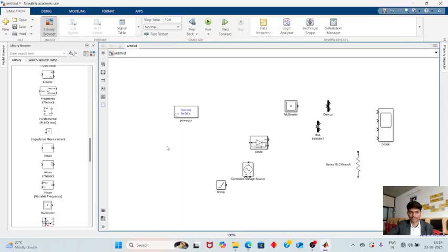Hello everyone, I am S7, roll number 15 from TY Electrical, and I am doing the simulation on the power diode. These are all the element blocks we require. We simply take them from the library browser. We require one power gui, one ramp function, one control voltage source, one diode, then a multimeter, one DMUX, a bus selector, a series RLC branch, and a scope.